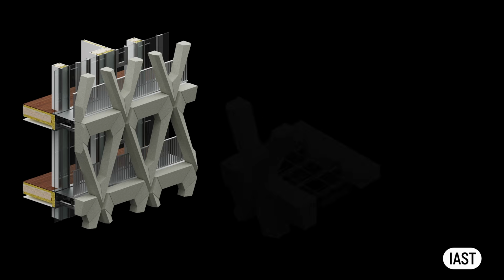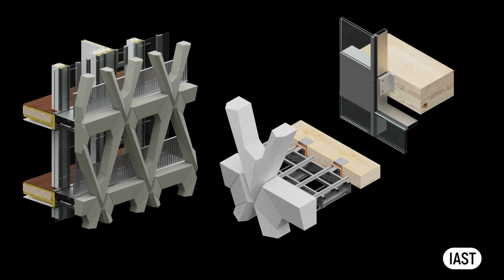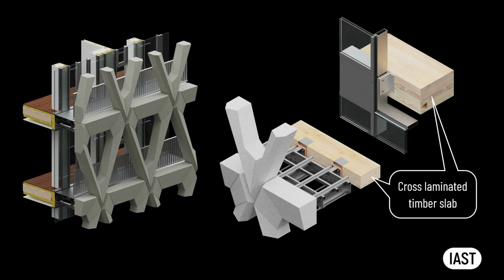Lastly, we should talk about mass timber used in our case study. In the parts of facade module, we discussed the balcony connection to the cross-laminated timber slab. We have already mentioned that timber can rot if exposed to moisture. Therefore, weather detailing around connections to timber and any facade penetrations, as well as the management of interstitial condensations, are critical. Mass timber structures are most vulnerable to water ingress during construction.